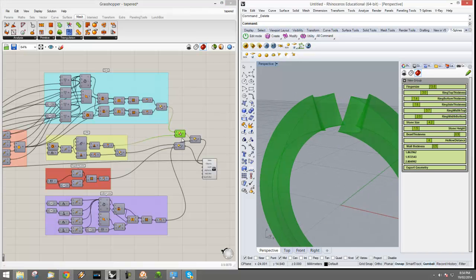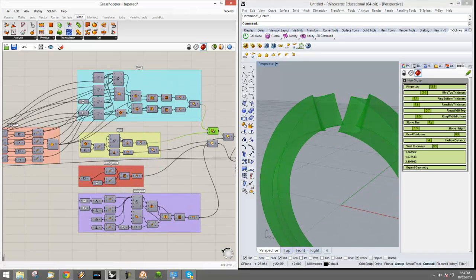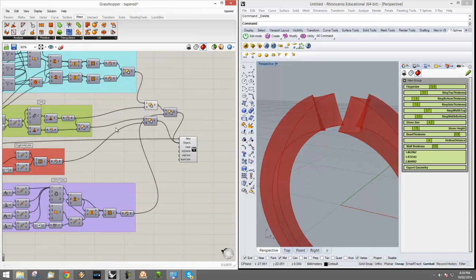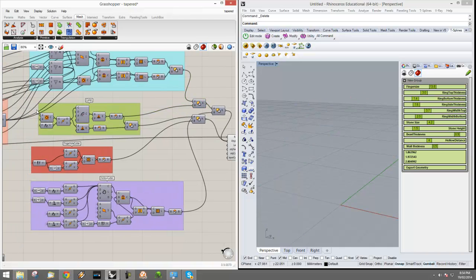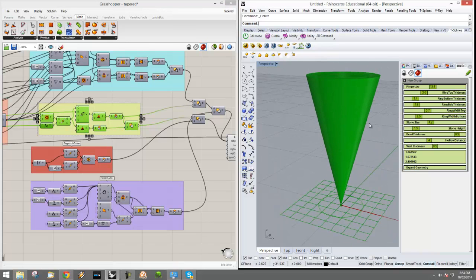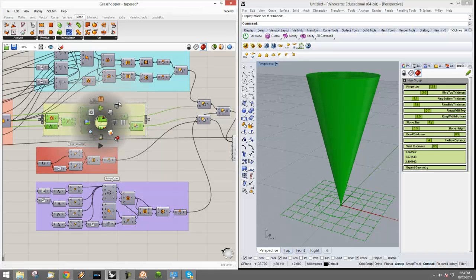Okay, what you're seeing, the cutout over there, is this over here. So by the same process of creating a couple of surface and curves and lofts, I've created the collet. Okay, so if I show the collet, let's hide this again. So if I show the collet tools, you can see that I've created two curves, extruded them towards the center, and simply done a Boolean difference with the finger size curve. So the same way that you work in Rhino, nothing's changed. Let's hide all those again.